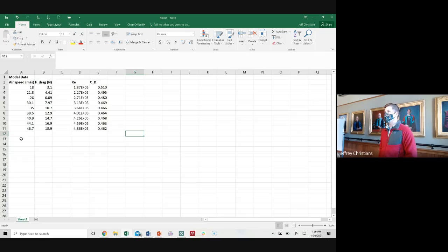So what's the other way that we could do it? Well, we could change either density or viscosity. Those both show up in the Reynolds number. So how would we change density? We could go to different pressures. We could change density by a factor of 10 by going from 1 atmosphere up to 10 atmospheres. But then we would have to be doing a wind tunnel experiment with a pressurized wind tunnel. You could do it, but again, you lose some of the advantage of a quick and easy experiment.